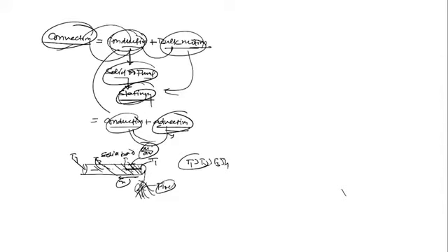And when the temperature gradient exists, that I told you, is the definition of conduction. Conduction is the transfer of energy or heat in a stationary medium due to temperature gradient. Whenever a temperature gradient exists in a stationary medium, that causes conduction to take place. When we start heating, the molecules of the solid are fixed at their position, and at this point the temperature is T1, at this point T2, and T1 is more than T2. Then that causes the temperature gradient dT upon dx, and that causes the energy to get transferred, and that is called conduction. Clear?